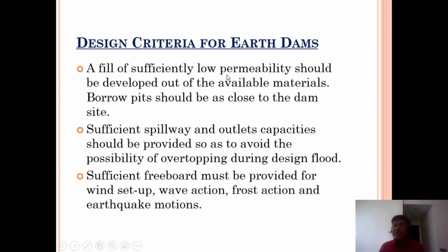I just summarized here, taken from the different literatures and codes, how they do the design of an earth dam. Here are the basic requirements, because we have to consider first everything from the materials itself and the proper analysis that we are going to do. A fill of sufficiently low permeability.